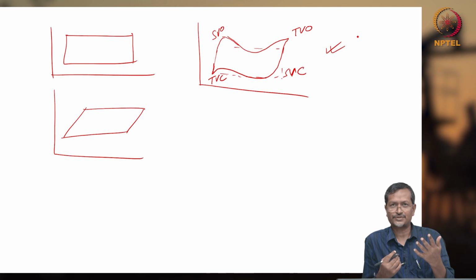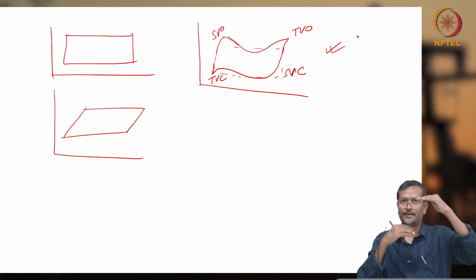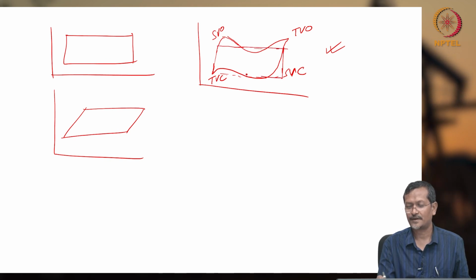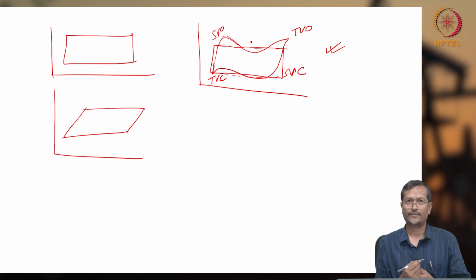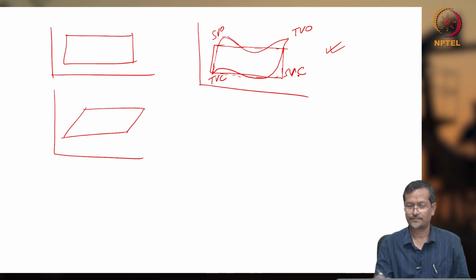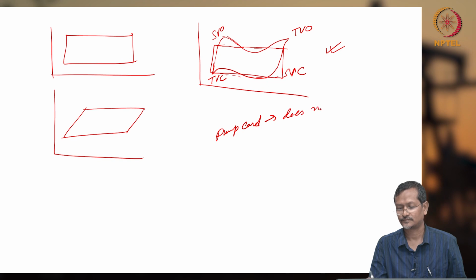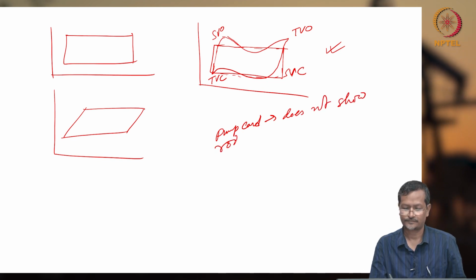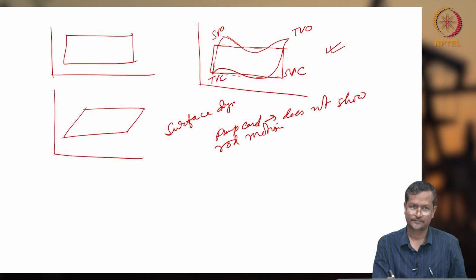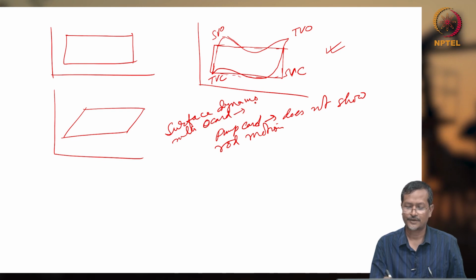So there are several wave equations. These wave equations eliminate the rod motion and other motions, and give only the pump area dimension. So in that case, what will they do? The wave equation will remove all this unnecessary part, and make a smooth curve. So that will give your pump curve. So there will be two curves, one will be the surface dynamometer curve, one will be the pump curve. The pump curve does not show rod motion, but the surface dynamometer curve shows all.